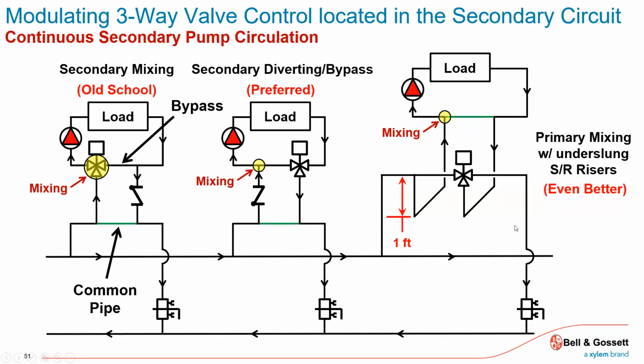What's his flow rate? But the actual amount of flow that I need might be pretty low that I'm sending across this crossover or across this one. So instead of putting the valve up here or up here, let's put it over here on the crossover. Now it's much smaller because now it's truly, hey, over here I'm pumping, I'm just throwing numbers at you, 200 gallons a minute, I'm going to inject 10 or 20 or whatever. Well, if I'm pumping 200 GPM and I have the valve over here, that valve's got to contend with 200 GPM. Regardless of the port's moving, it's 200 gallons a minute.